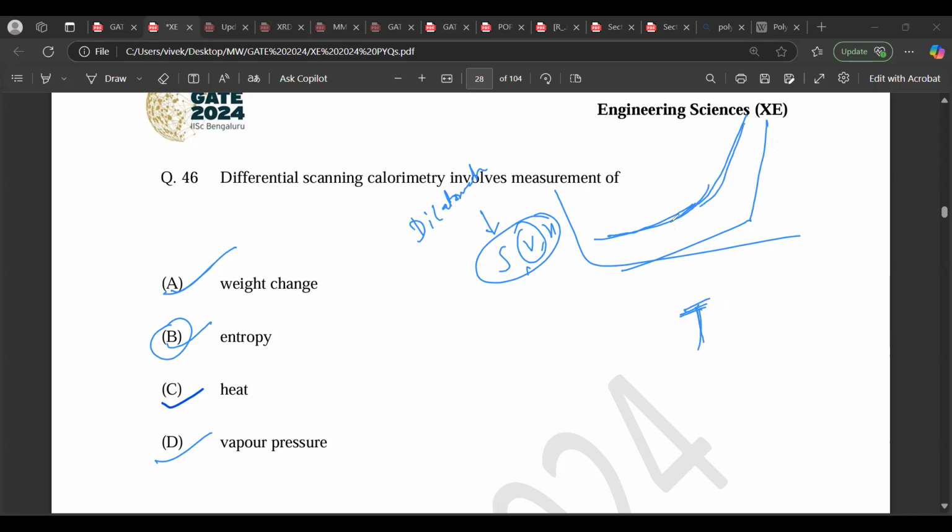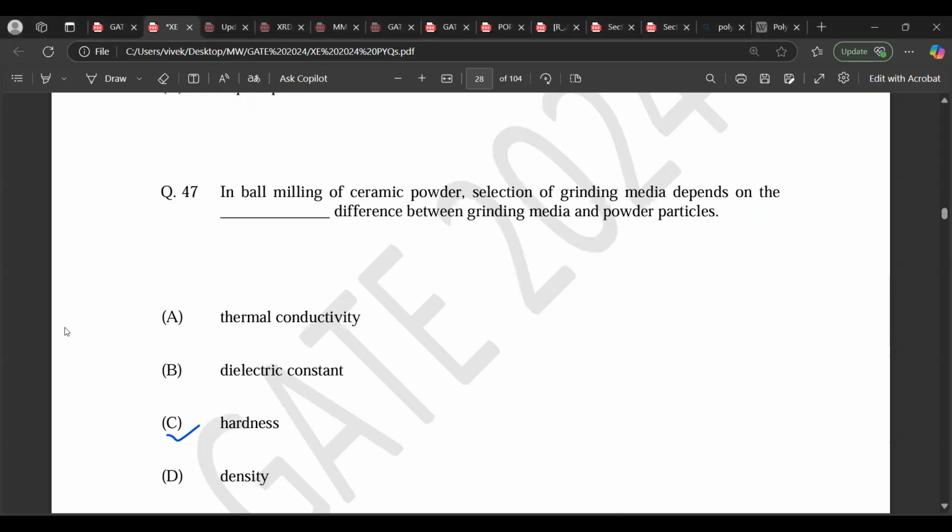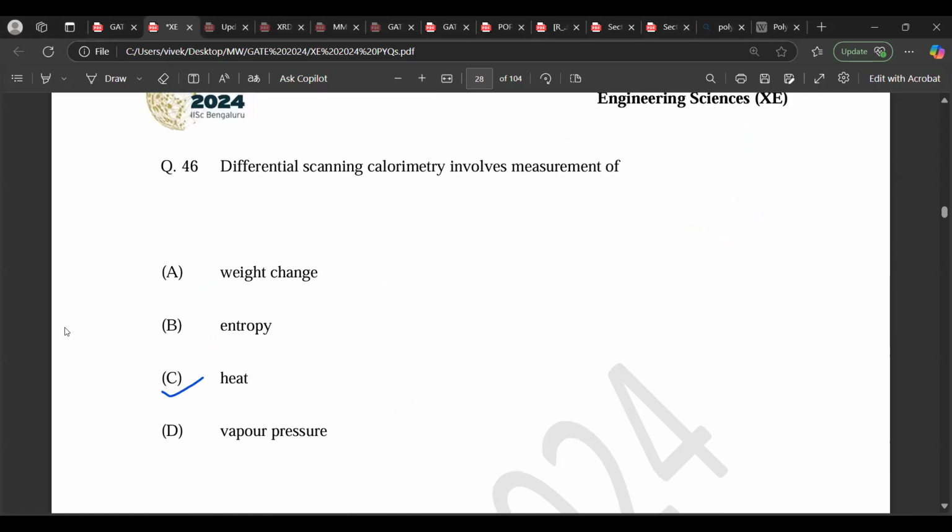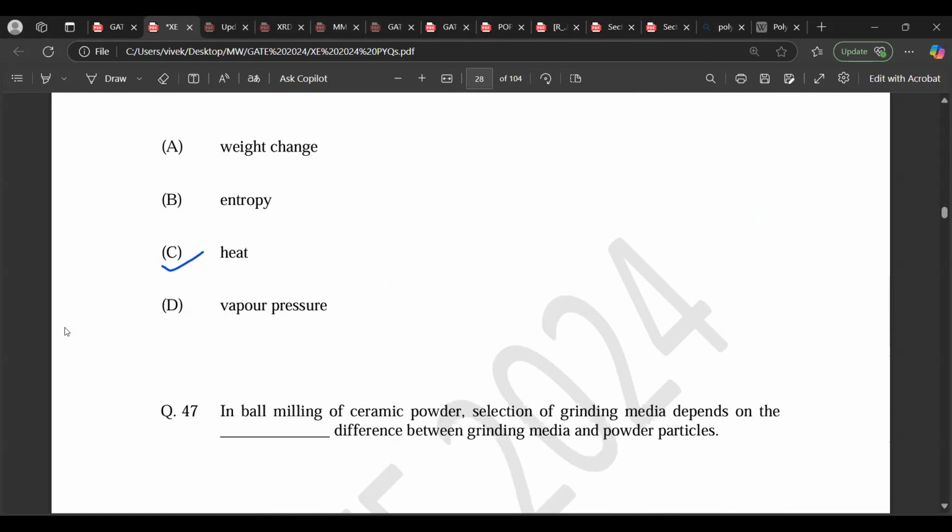And this is for glass, where this tangent will give you the Tg, and this is the typical melting temperature. Before that they are viscous or liquid, before they become solid. So this graph we know. It's a standard graph that we use for Tg, Tm, and entropy, or even the second order or first order transition explanation that we give. So the entropy is something that is plotted in dilatometry. It's a no-brainer, and you all can easily understand it. If you want to learn more about this, you simply need to know which graph is plotted in a particular piece of equipment. If you remember the graph, you can easily plot it.